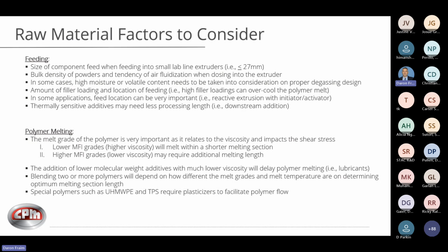So when we're dealing with reactive extrusion, where we put the initiator, the activator, and then thermally sensitive additives may need less processing length. So you may need to add those farther downstream.